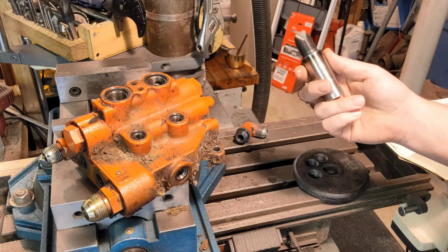I've used this method before, and though it's not as crisp and smooth as a factory-made tap, it's very predictable in that you can't really do much to mess it up. It only works okay, but it's consistently okay. They don't break off, they don't have any other ugly surprises. So I cut a 7/8-14 threads onto some water hardening steel rod and hardened and tempered it, and then ground back the 4 leading bevels.